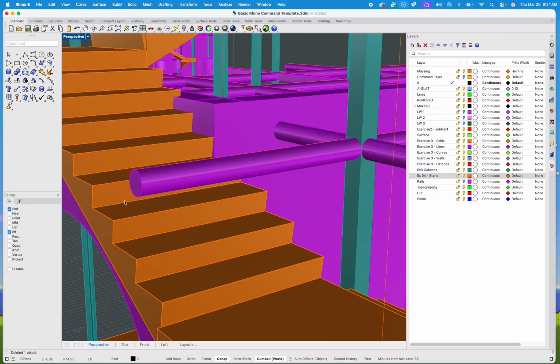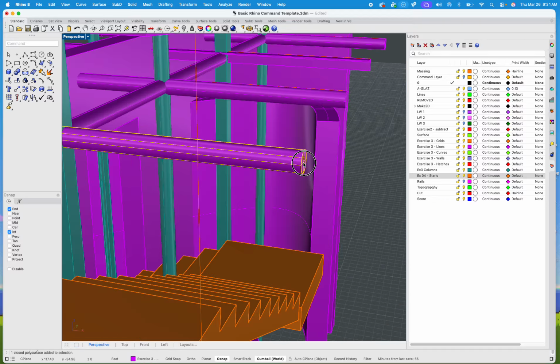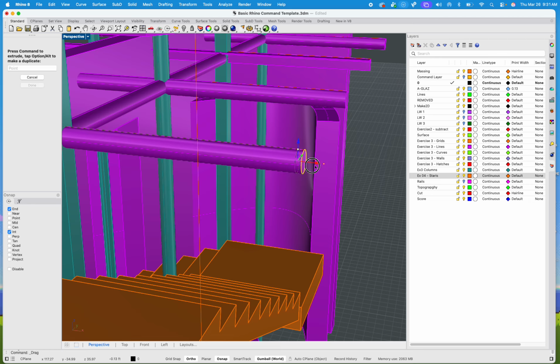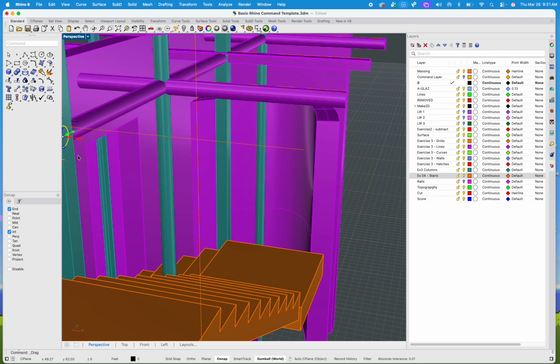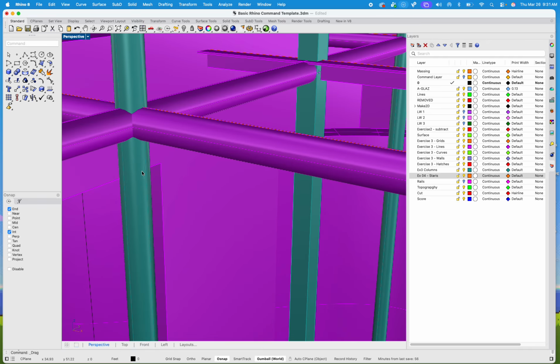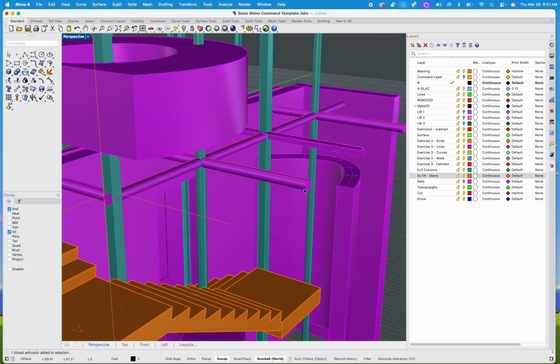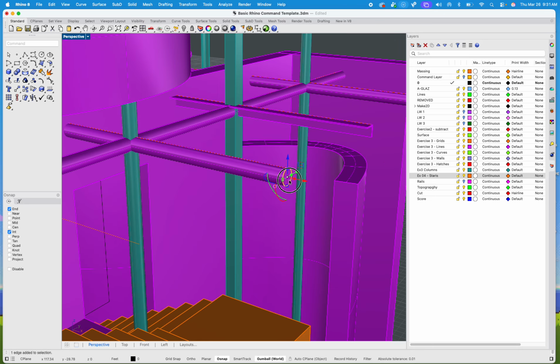So make sure you're holding that command key and moving some faces out of the way. I usually go right back to my grid, and right back to my grid because I don't want to get rid of the entire piece. And again, holding Shift as I move those so that it remains. I could also trim it, right? Or Boolean difference, but let's face it, that takes like 3 to 5 clicks, and this one just takes 1.